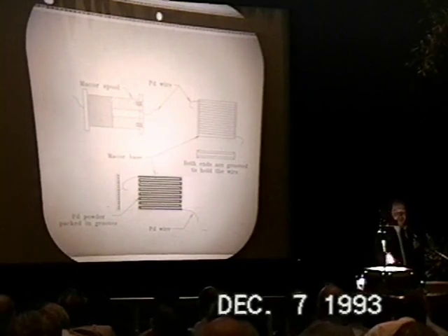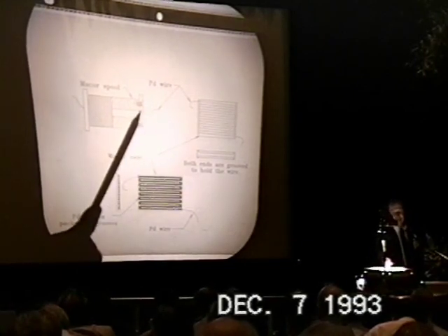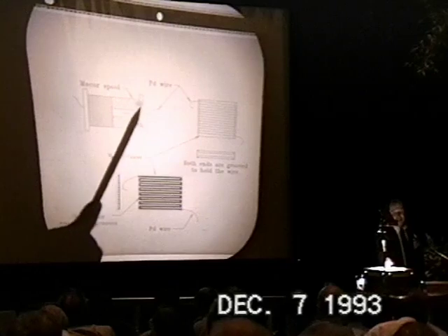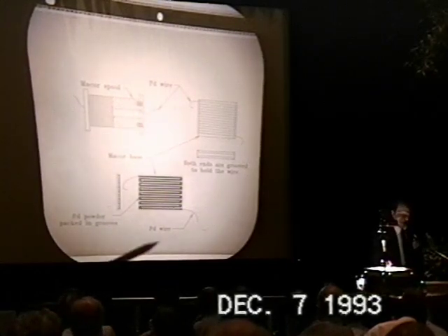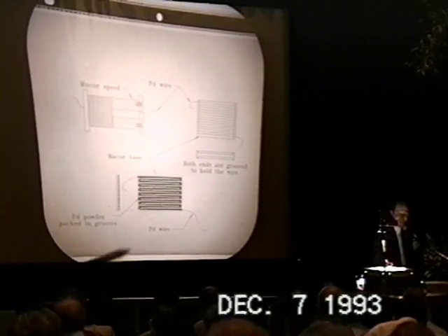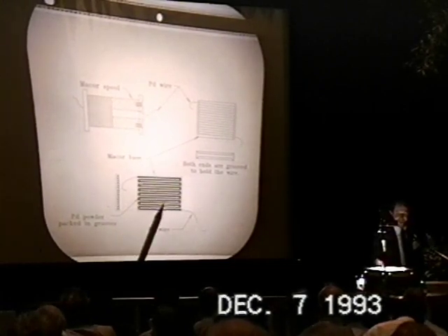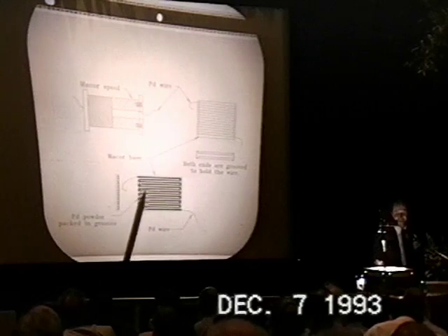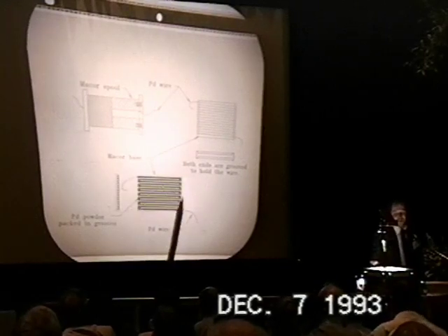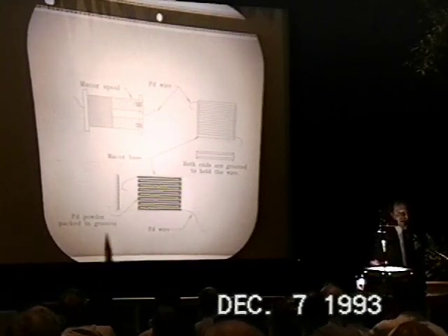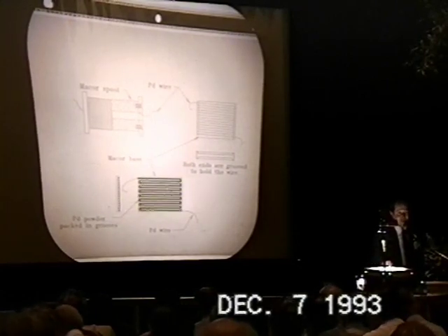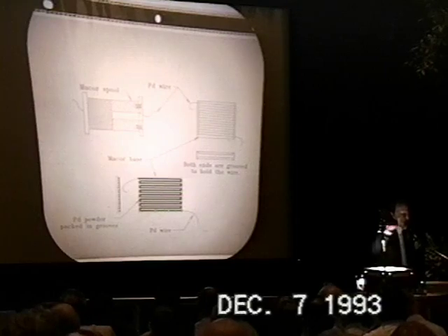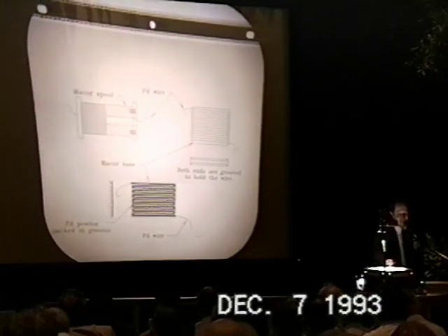Here's a picture of the spool. The wire simply comes in, is held by this down track on the end, and then is wound around in many windings. I'll talk first about the wire, but then I'll come back, and since it's here, I'll show the powder track. We actually press palladium powder into this track, covered with a Teflon filter paper, and then a block of Teflon that's held together to hold the powder in the track.